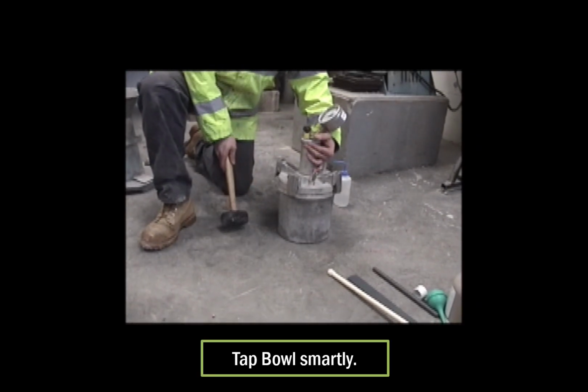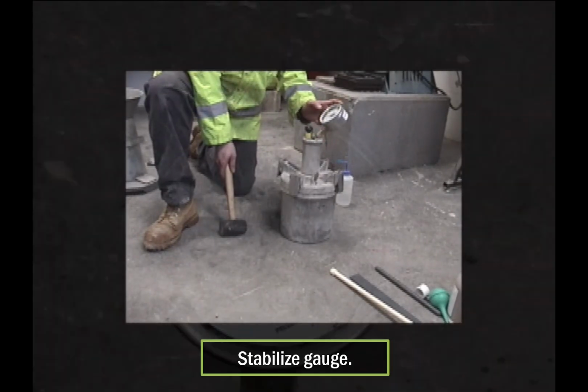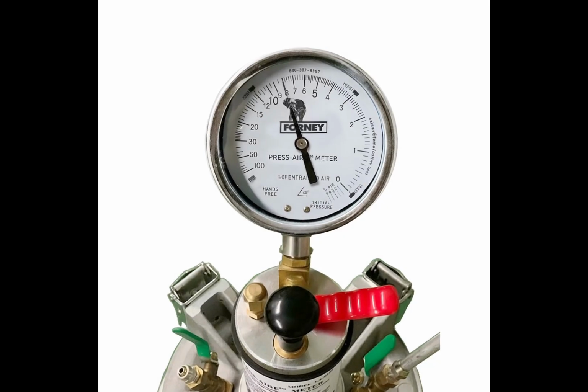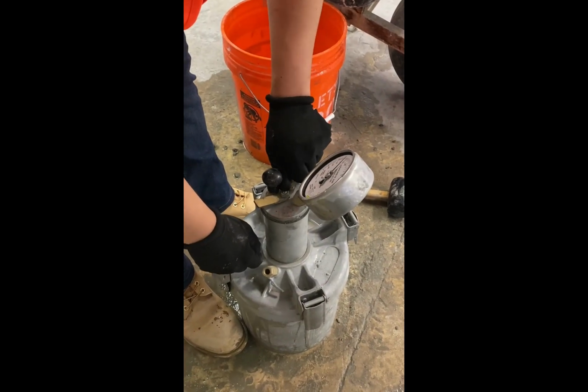Tap the sides of the measuring bowl smartly with the mallet. Lightly tap the pressure gauge by hand to stabilize the gauge hand. Read the percentage of air on the dial of the pressure gauge. If the air content is 8% or less, record the air to the nearest 0.1%. However, if the air content is greater than 8%, record to the nearest 0.5%. Release the main air valve.